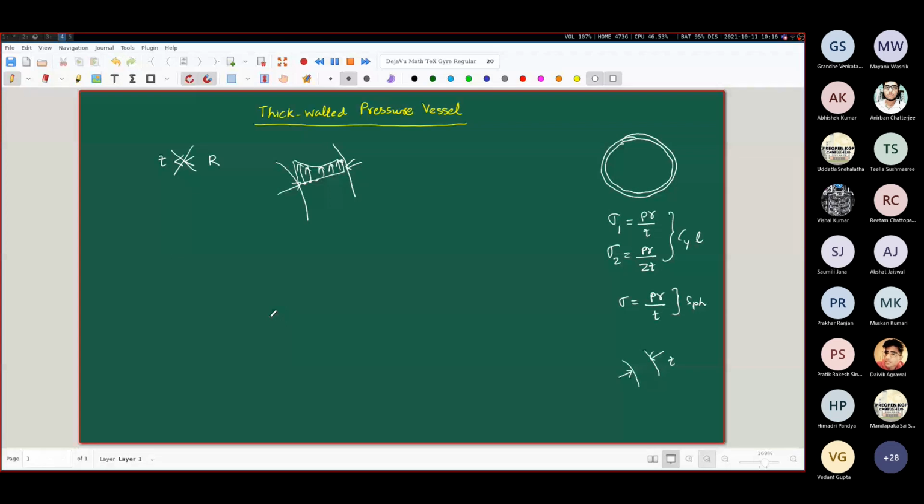The kind of things that you get to study there has a direct connection with this. Okay. So let me just tell you that maybe as part of your derivation of your Navier-Stokes equation, you have come across an equation like this, where capital D represents the material derivative, and this is something like divergence of the stress tensor plus rho B, where this B is the body force per unit volume.